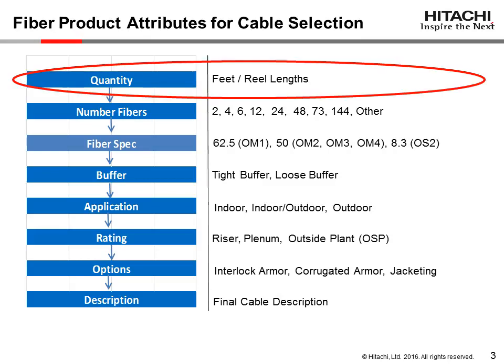Quantity is normally the first requirement mentioned. In most installations, the requested quantity is frequently a point A to point B special length suited for specific installation runs. This is very different than copper category cables, which are universally ordered and supplied in 1,000-foot packages and can be used in multiple locations and jobs.